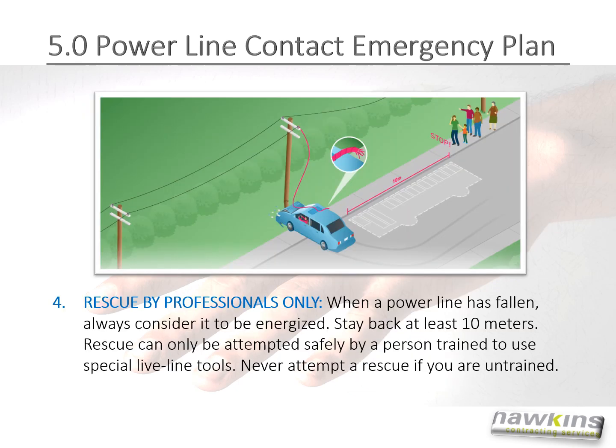Fourth, rescue by professionals only. When a power line has fallen, always consider it to be energized. Stay back at least 10 meters. Rescue can only be attempted safely by a person trained to use special live line tools. Never attempt a rescue if you are untrained.